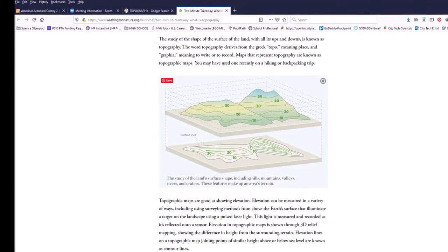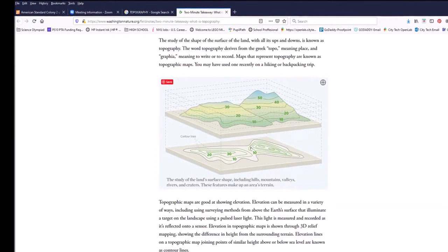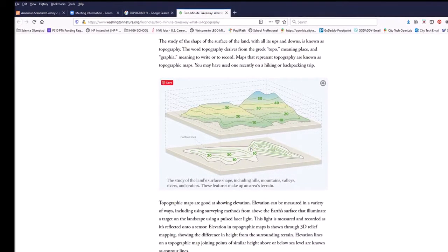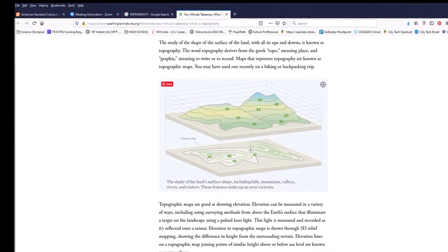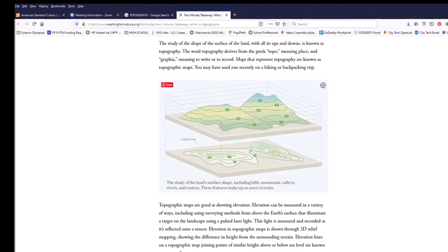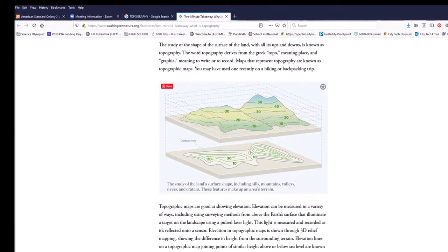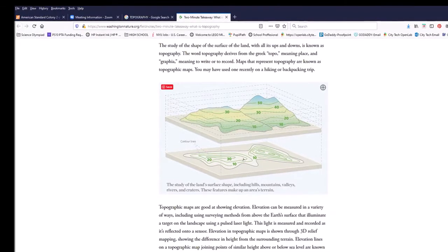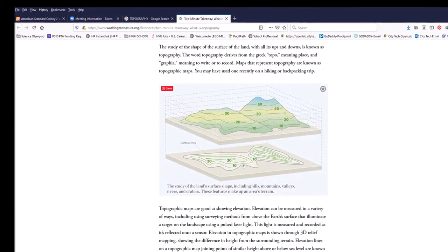This is exactly what you're doing when you take site planning or surveying. You'll walk up a mountainside or hillside, take your transit, measure the elevations of those specific spots, and move along the mountain until you've mapped out all those contours. You'll translate that into a two-dimensional drawing, because we need some way of representing vertical heights in two dimensions, right?